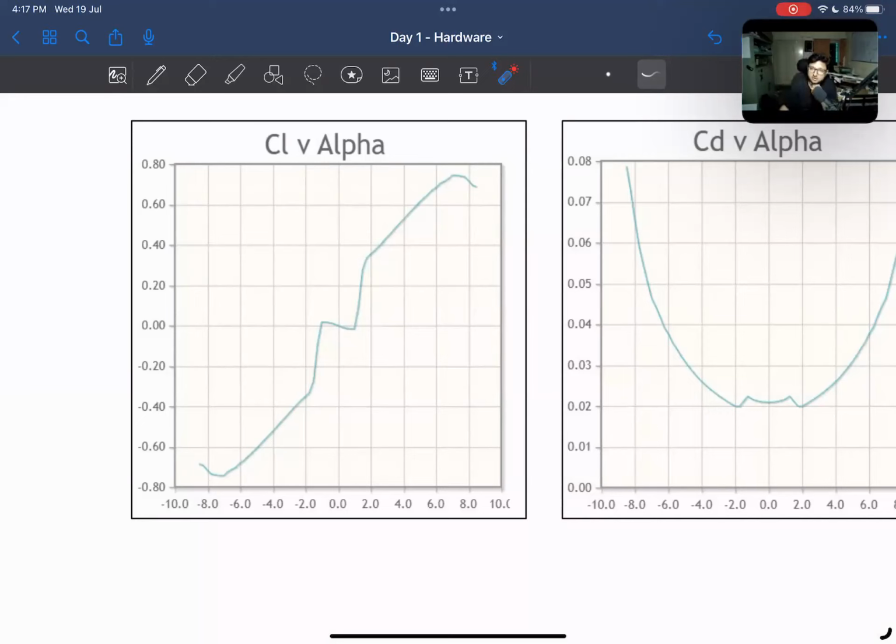However, that is not the case with asymmetric airfoils. For asymmetric airfoils, you will get very nice lift at zero angle of attack, but these airfoils perform very badly at negative angles of attack. The symmetric airfoils don't perform badly at negative angles of attack. The term symmetric also means that if you vary them across positive and negative angles of attack, the behavior is symmetrical, only in the exact opposite direction.